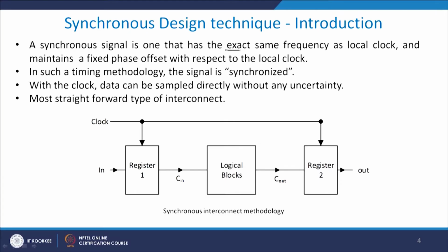Let us look at the synchronous design technique. As I discussed with you, we will have the same frequency as the global clock, the local clock. A synchronous signal is the output signal, which you are giving as the data, and which has the exact same frequency as the local clock. So, you have a local clock driver which will drive the system, and your synchronous signal will have the same frequency as the local clock and will maintain a fixed phase offset with respect to the local clock. Your data, the synchronous signal, should maintain a fixed phase offset with the clock. As long as it is able to maintain that, there is no problem in functionality.